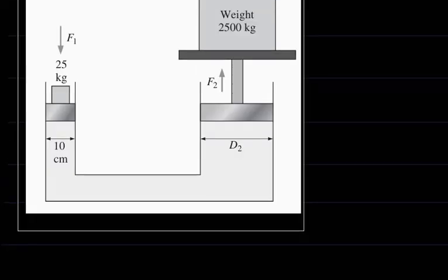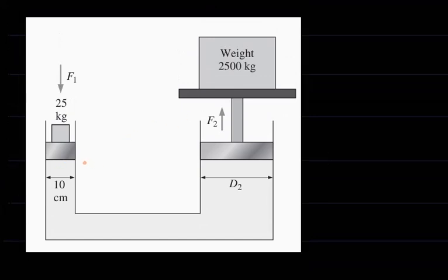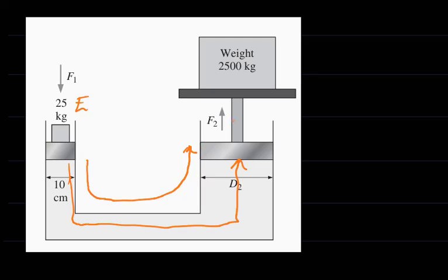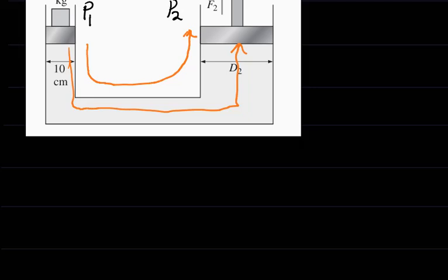So here, this is a question on hydraulic press. A hydraulic press is a device that is used to transmit pressure from the effort to the load. Effort is applied at one arm of the hydraulic press, then it uses fluid to transmit pressure from the effort to the load so that the load will be lifted up. So the principle of hydraulic press is this: the pressure that is generated at the effort, P1, is equal to the pressure that is transmitted to the load. So P1 is equal to P2. That is the principle of hydraulic press.